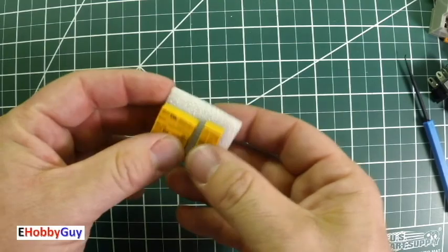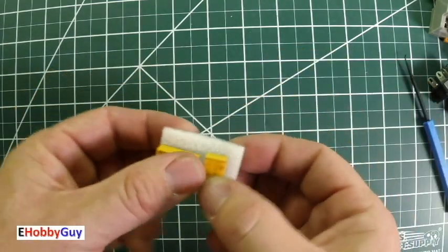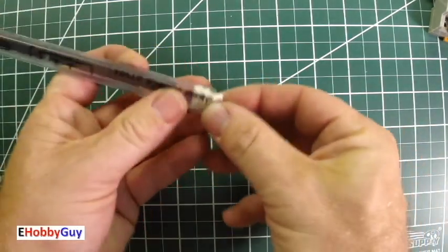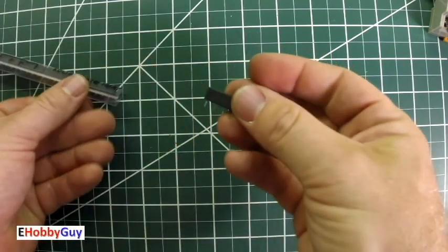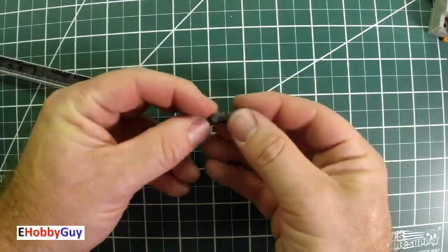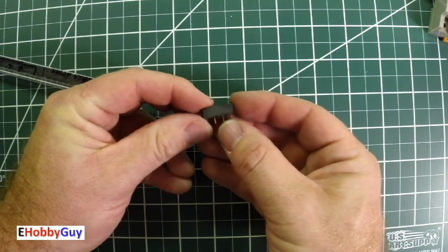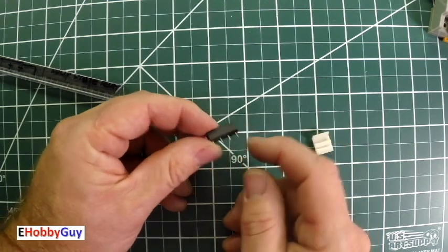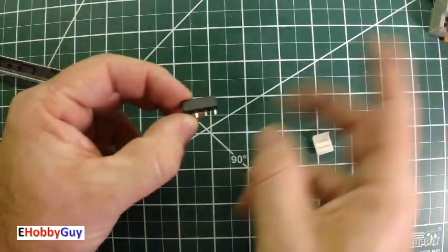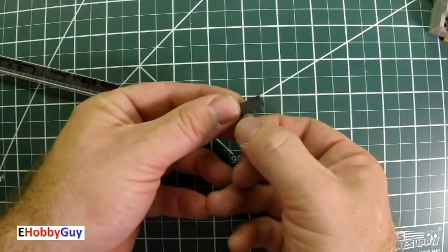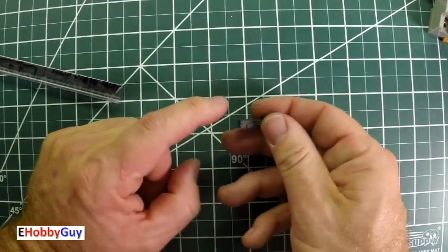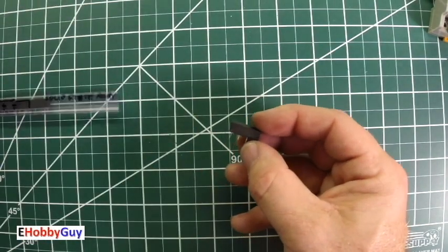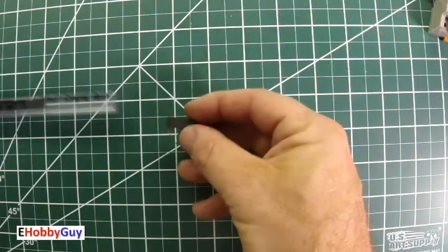Very common PCB mount. These take very low current to actuate. I do have solid state relays here, a little sleeve of them, and these are semiconductor based, not using a coil. I would have to look at the spec sheet definitely for this, but two of these are what would be considered the coil, though it's not, they're the activation contacts, and two, I believe, this one's normally open, so it's a Form A relay, solid state. So this is a Form A solid state relay. It only takes 8 to 10 milliamps to activate this, which is very good.